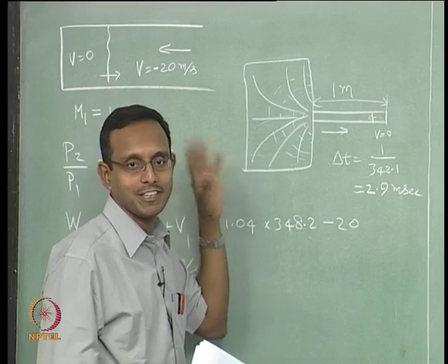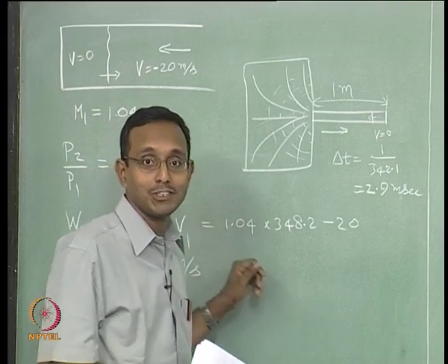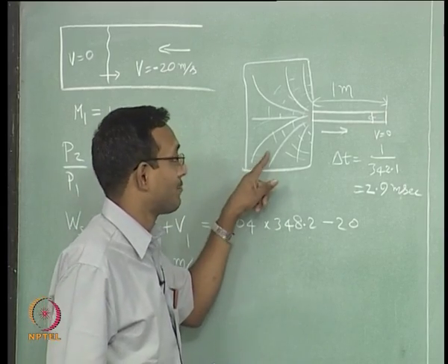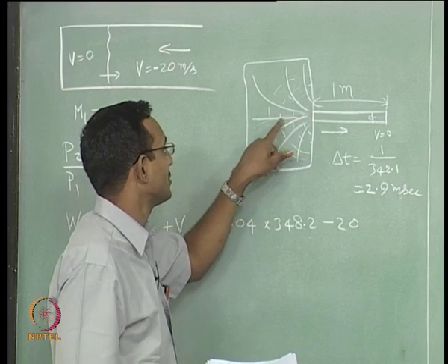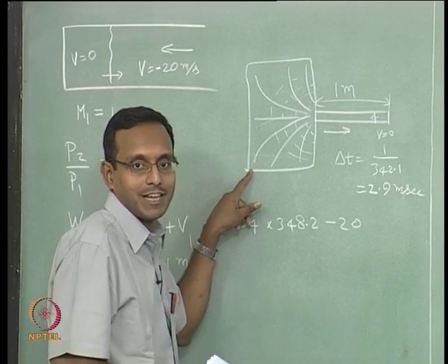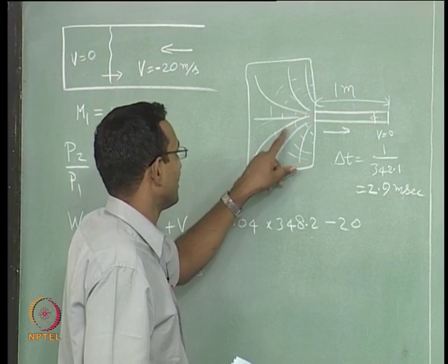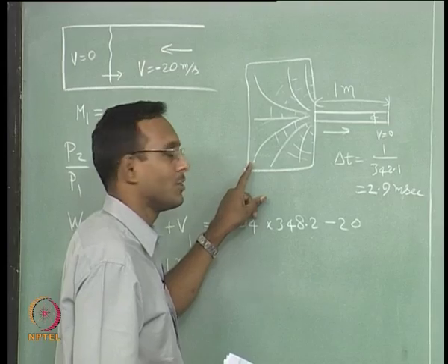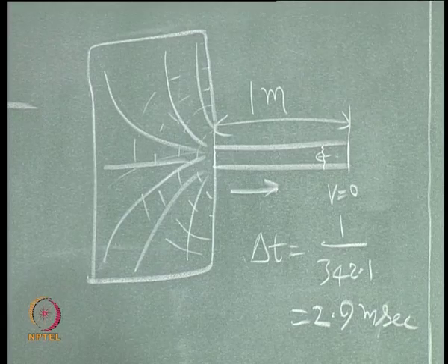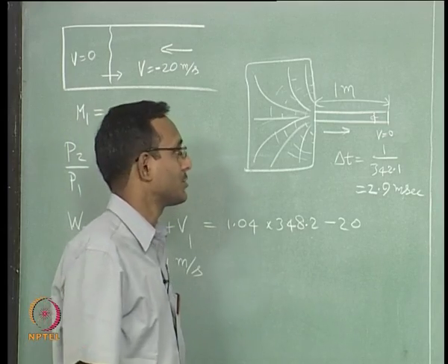We will talk more about it when we are thinking unsteady flows, but anyways, when it is expanding, it is going to have lesser and lesser strength, which means it will cause lesser delta V, but it so happens that that is enough for this case. As I go this way along the streamline, the velocity is going to be lesser and lesser. When I come to this corner of the streamline, it is stagnant gas, right. If that is the case, then when the shock keeps on coming, the delta V required to stop this fluid is going to be lesser and lesser. Eventually, the shock becomes very weak and stops completely. Nothing more needs to be done. That is what really happens inside if I ever stop a flow.